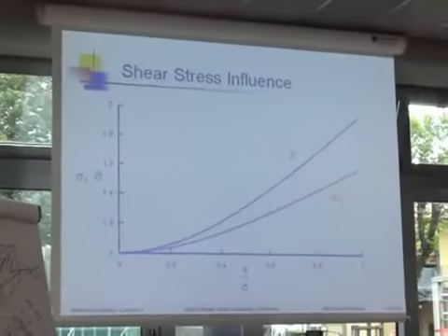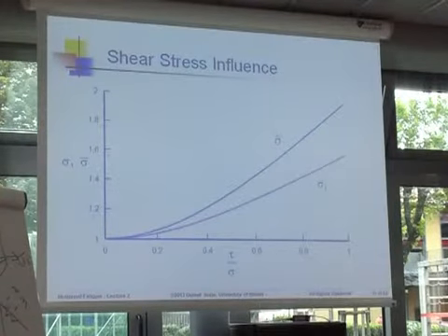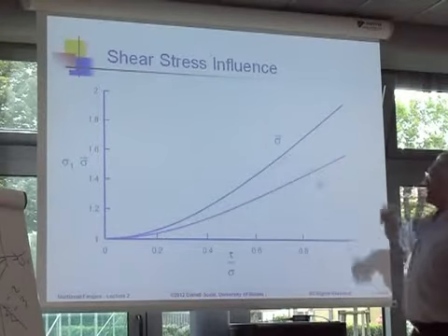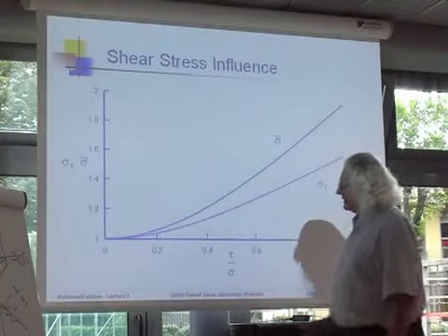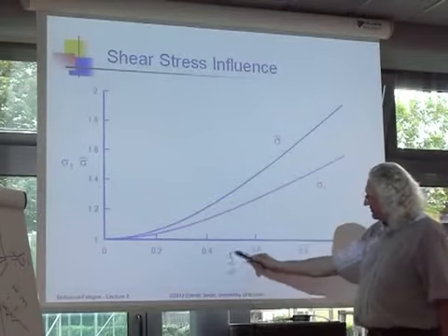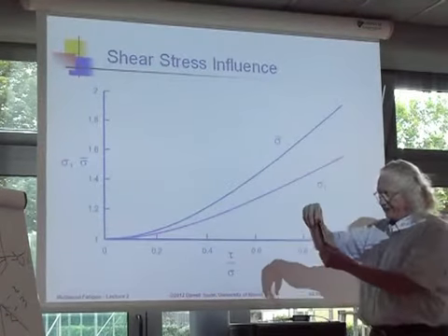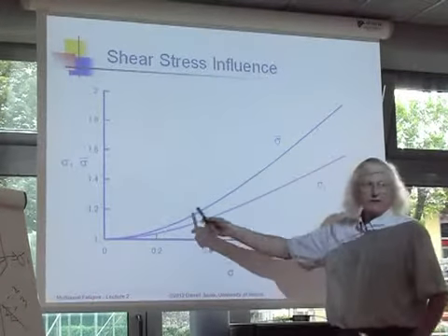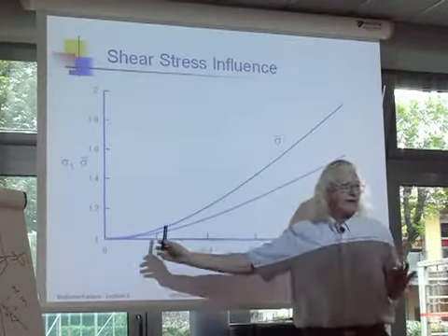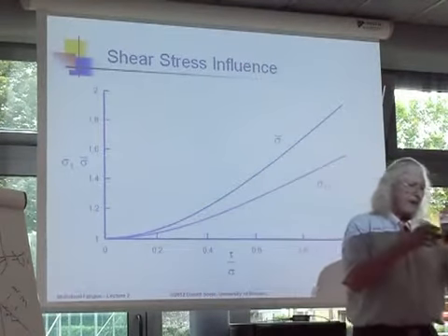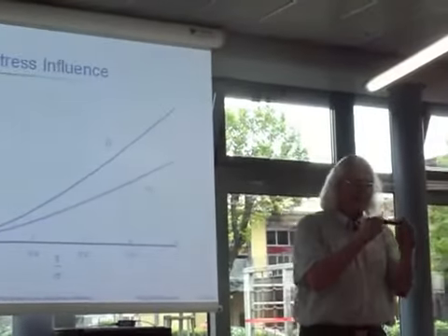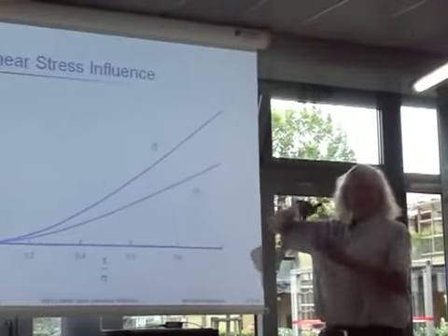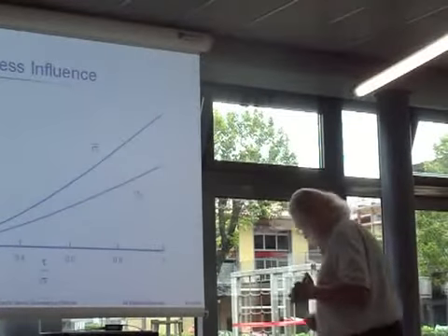I always like to talk a little bit about the shear stresses and to look at the difference between the principal stress and the equivalent stress that you calculate. If the ratio of shear stress to tension stress applied on my tube is only a third or so, then it doesn't matter which stress you pick. They are about the same. It matters, with either equivalent stress or principal stress, when the shear stresses dominate, way out here. Then there's a big difference in these two stress levels.